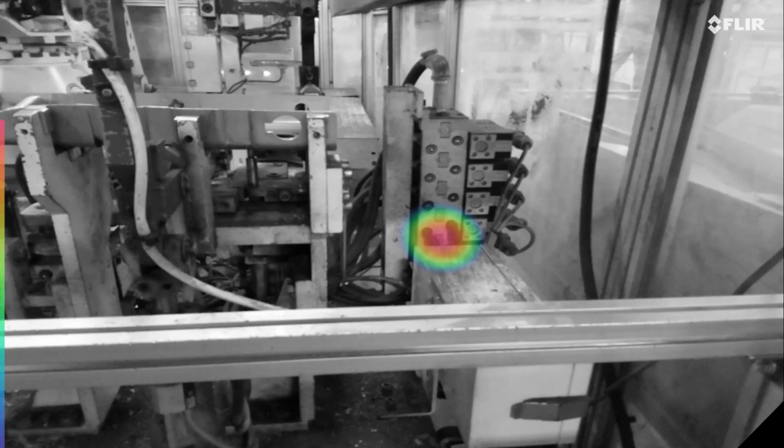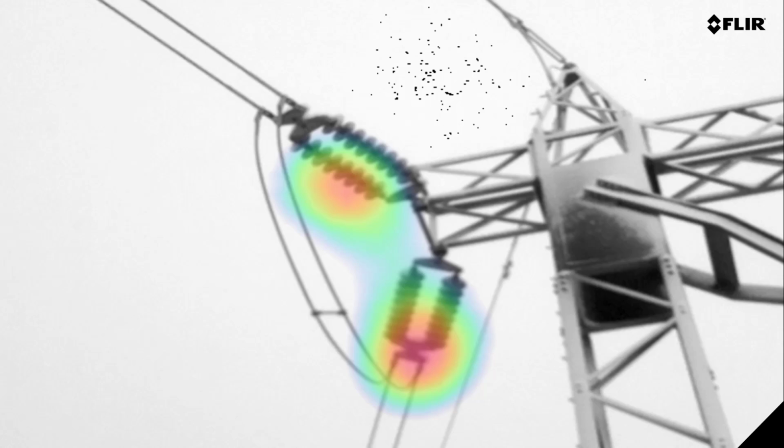Now here we have a solenoid valve leaking. Right? It's a very common occurrence you might see in the field. You can see we have identified exactly where it is occurring based on that ultrasound technology that we're using. Here's an example of surface discharge on insulators, electrical power cables, something that we definitely want to be able to identify as early as possible before it can do much damage to our system.